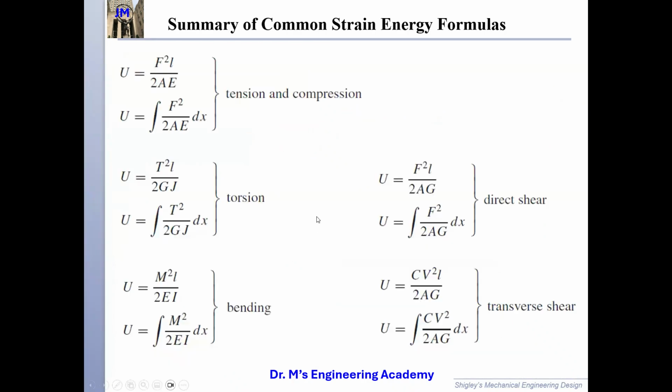So this sheet covers all the equations: tension, torsion, bending, direct shear, and transverse shear. Usually we don't have the direct shear directly. For some very simple cases, we have this one. We usually have 1, 2, 3, 4. And if the beam is a cylinder, you just cross it out and only think about these three. These three are the dominant loading conditions.